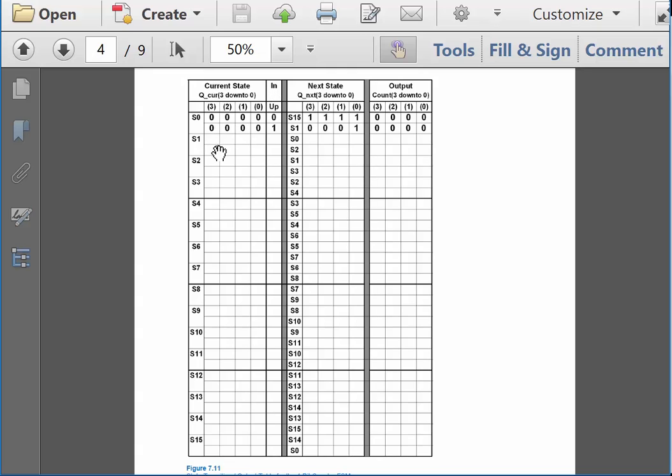And another thing that we can do with a counter is we want to use what's called state encoded outputs. What that means is that we want to encode the states such that the current state code itself is the output that we want. And in a counter, this works very well, because if we assign the state codes in a binary fashion, then as I traverse through the 16 possible states, the state code is the 4-bit representation in binary of that state. And so the current state can be the output itself. And that's reflected if you come through and you list the current state codes out.